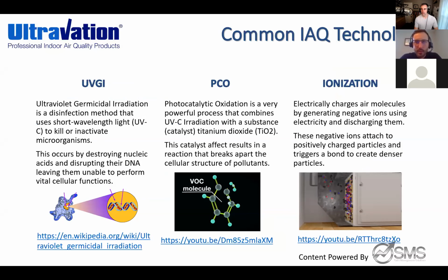So I did want to just reiterate the different common IAQ technologies: UVGI, PCO, and ionization. We do know UVGI, and this is an important thing about UVGI, and the reason we keep on bringing it up. That is what ASHRAE recommends to kill viruses and bacteria. UVGI only comes from UVC lamps, so that is ultraviolet germicidal irradiation. That's the disinfection method that uses short wavelength light to kill or inactivate microorganisms.